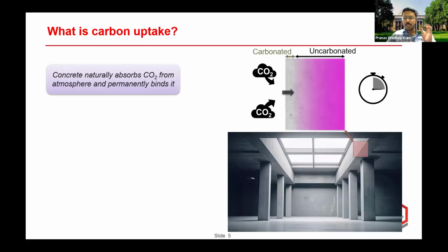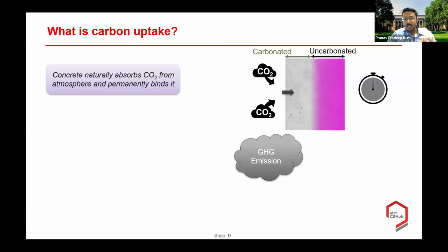However, this process occurs slowly over a period of time, which could take several years. And we can observe that the carbonation front, or the depth of carbonation, increases over time. While there are several factors, ranging from material properties to environmental conditions to the exposed geometrical surface of the concrete, which determine the extent to which the uptake has taken place, we can say that this natural mineralization of atmospheric carbon dioxide, that is carbon uptake, by concrete elements offers a great mechanism for neutralizing a portion of their life cycle greenhouse gas emissions.